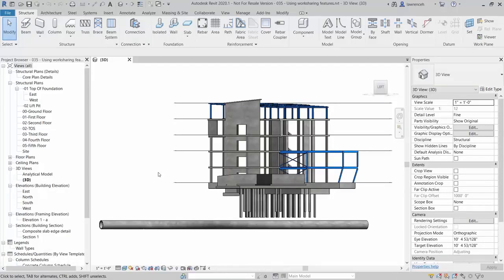Now, if the audit fails and you still can't recover a Revit model, then the next step is to go ahead and look at the journal file. So the journal file may indicate families that have been corrupt, and you can then get the element ID and search for that element ID and then delete the families that are causing corruption. You can then try and run the audit process again.